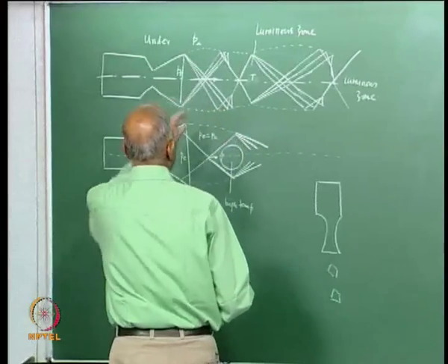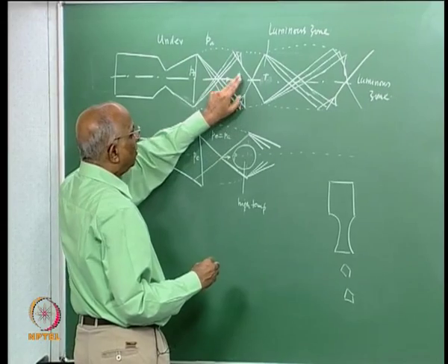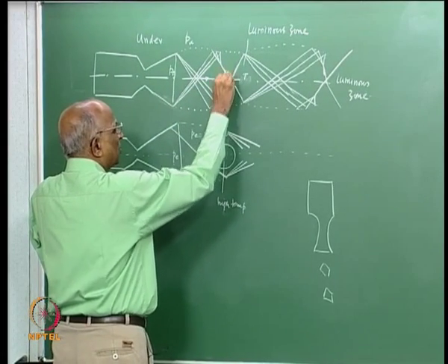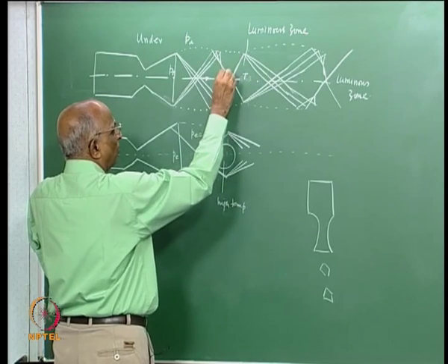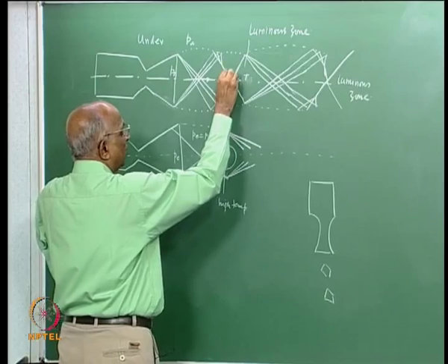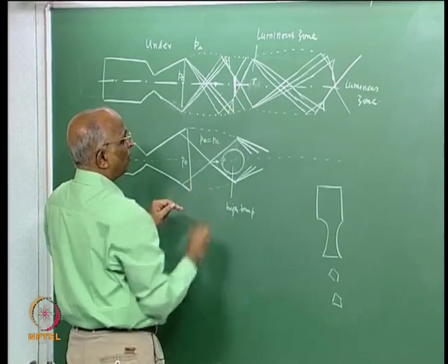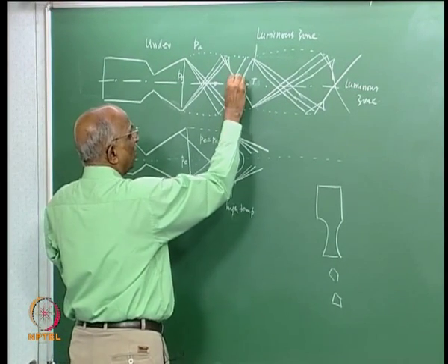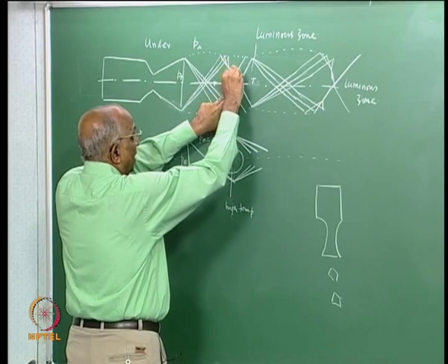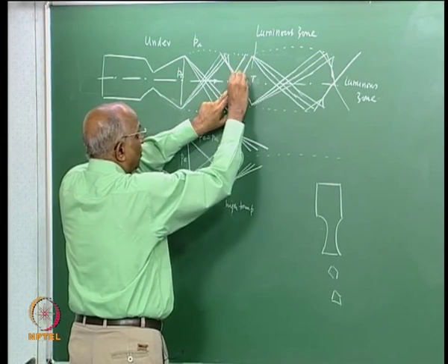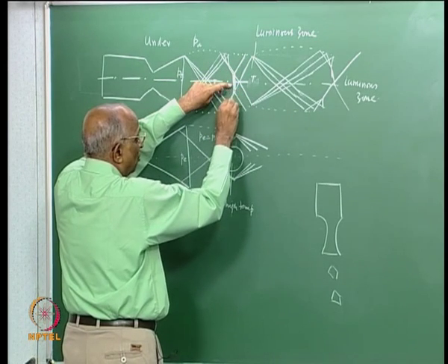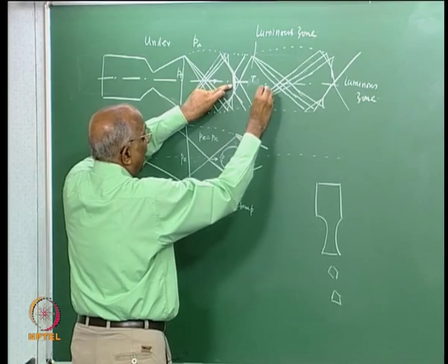Whenever I have these oblique shocks, when the oblique shocks interact, very often you get a Mach shock, a stem shock is formed, and instead of having a regular reflection like this, I have a Mach reflection, and therefore a shock is formed like this. Therefore, this shock wave is known as a Mach shock wave. That means I have an incident shock, I have a reflected shock, I have a strong shock over here. Similarly, I have the incident shock over here, reflected shock, and so on.